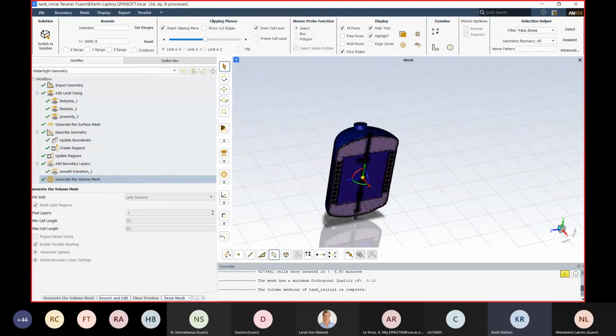The errors come in with aspect ratio when you have transverse flow, so it's going through at an angle and it's not perpendicular to the faces. Ideally, try to go for 100, that's your best. If you have to go more, it's fine. But anything other than your first cell, the second and more, should be less than 100.